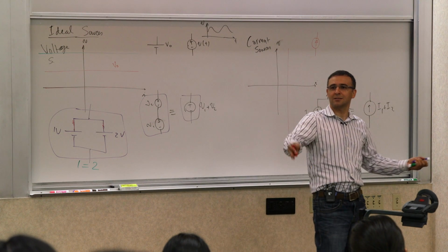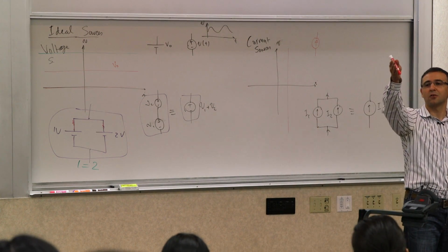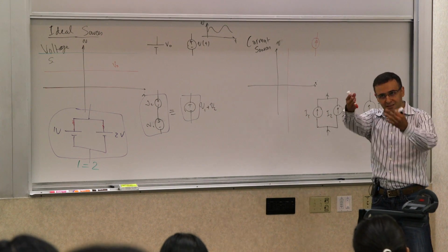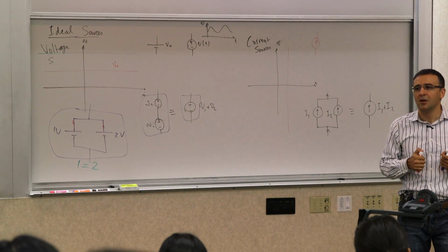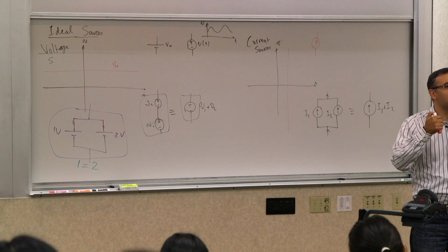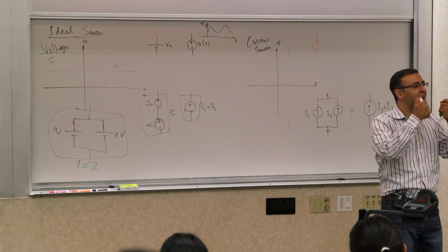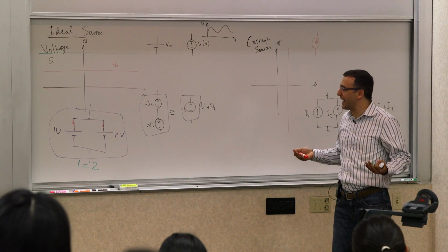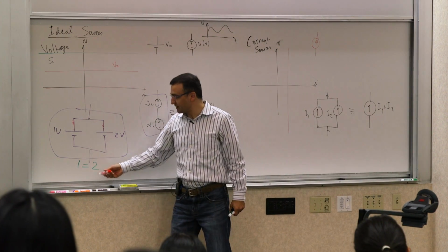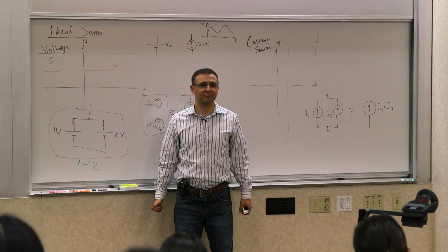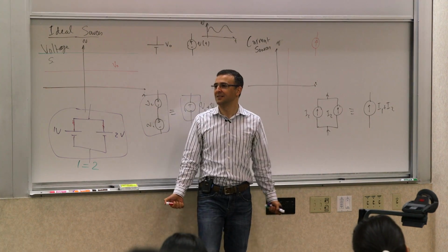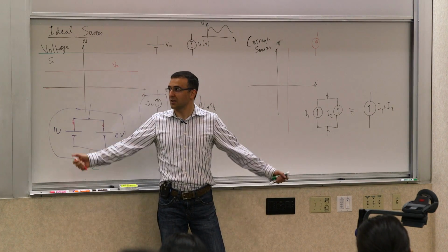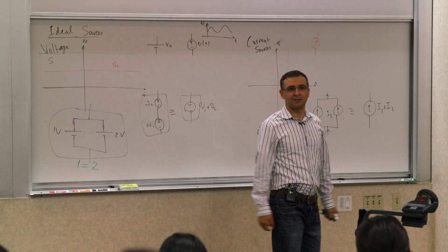I mean, you can solve what it is depending on what those resistances are, which basically goes back to your earlier comment about how strong they are and which one dominates which one and all those things, right? But in the absence of those things, my model is not capable of capturing the physics. Therefore, you can enforce random things. Can I write this in mathematics? I can. It's a false statement. Can I put these things, 2 ideal voltage sources in parallel? Yes, I can. It's an invalid statement.